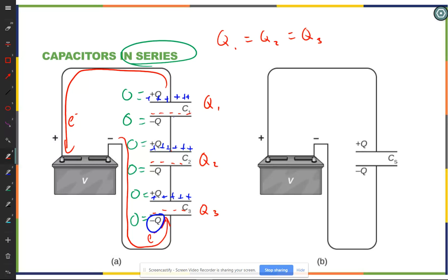Now remember, when I talk about the charge of a capacitor, I'm talking about the charge on one plate of the capacitor, because what's the net charge on the capacitor supposed to be? 0. Now you can do things in circuits to make it not that, but in a normal circuit, that's the way it should be. Net charge in the capacitor is 0. So this is not the net charge, it's the charge on one of the two plates. And we just take absolute value, that way it doesn't matter which plate you looked at.